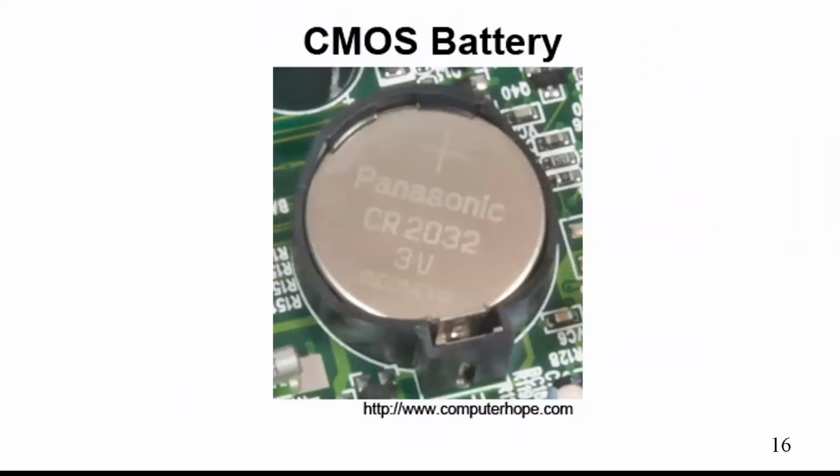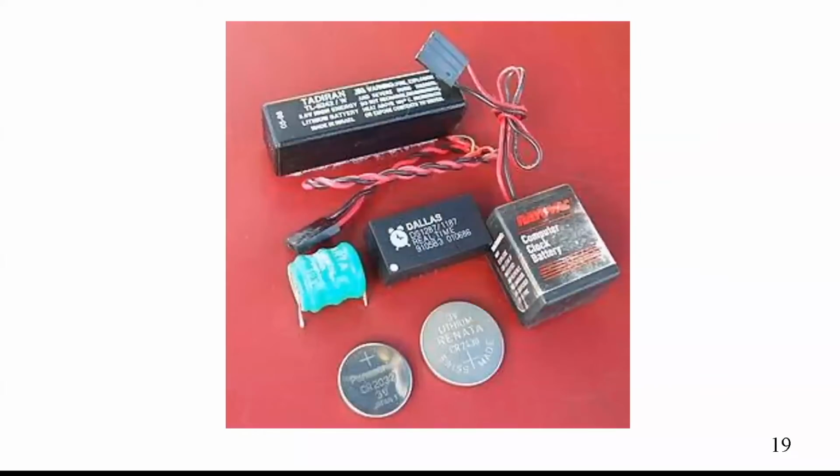To replace the battery, it looks like the current ones look like this. This is not in 99% of the computers now. It's a CR2032. And if you push on this little tab that holds it in, it's a little keeper, push it away from the center and the battery will pop out. Don't push too hard, like I did once. And once it's out, wait 5 minutes and push it back in.